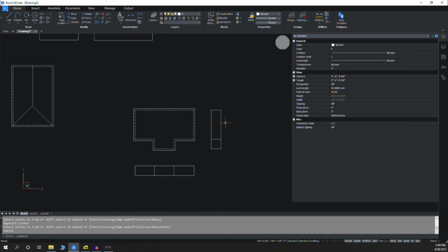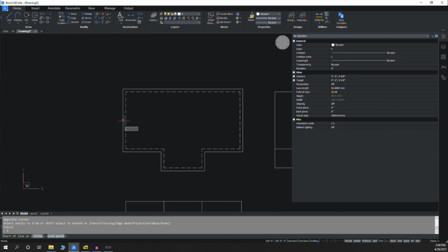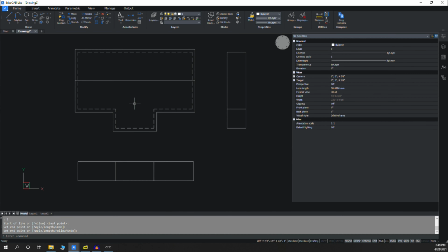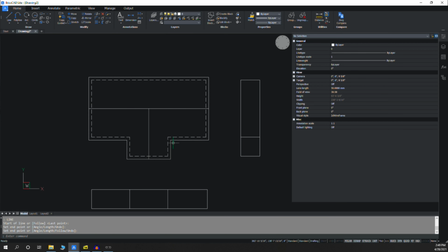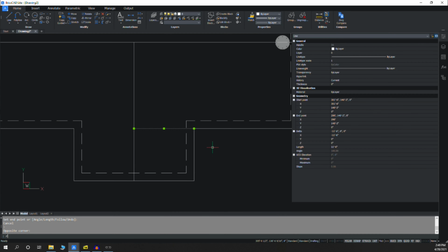So let's start with a simple gable roof. And gable roofs are really simple. All you gotta do is pick up the center line, the midpoint, and draw straight across. And then I can do the same thing over here. Pick up the center line and draw straight across. And what's really convenient is if the two pitches are the same, and in this example they happen to be, then the valley, which is the crease where they meet, is just 45 degrees.